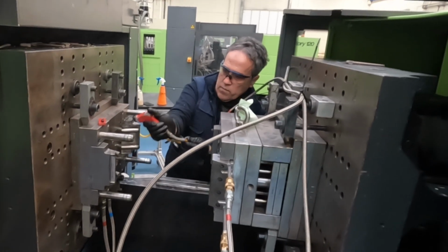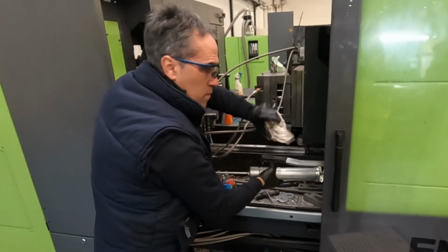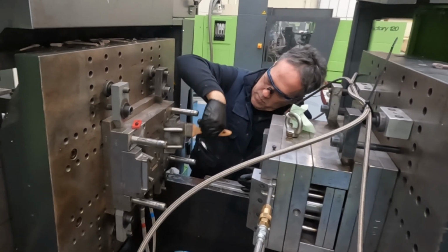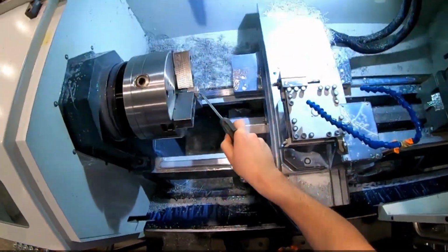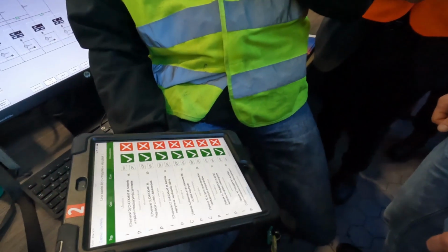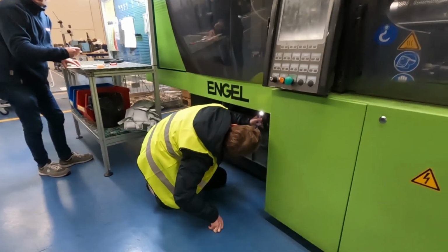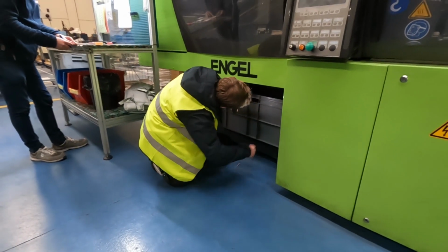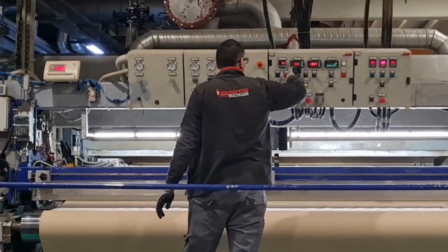This begins with autonomous maintenance through activities such as daily cleaning, inspection and lubrication of their machines, with the goal of keeping equipment in a good running condition. Equipment operators participate in small group activities to find and fix problems in their equipment. The TPM education pillar raises the knowledge and skills of machine operators, enabling them to detect early warning signs of problems.